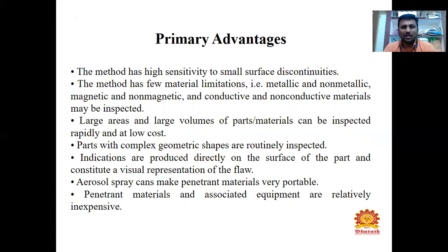Parts with complex geometric shapes are routinely inspected. Indications are produced directly on the surface of the part and constitute a visual representation of the flaw. Aerosol spray cans make penetrant material very portable. The penetrant material and associated equipment are relatively inexpensive. So these are the major advantages of the liquid penetrant method.